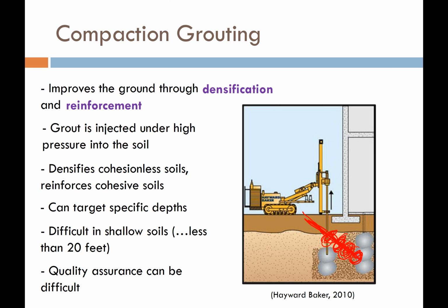But you have to be careful, because when you pressure grout this stuff into the ground, it can jack the ground and it can jack footings easily. And so you want to make sure that you have a professional who knows what they're doing and can monitor this stuff.